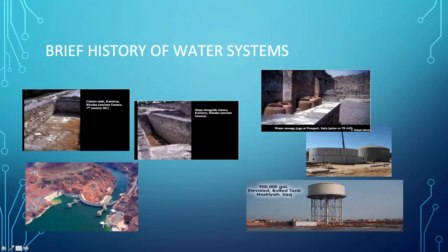These circular objects here are the intakes to the power plant and any drinking water supply that the dam is used for. Actually, no, not for drinking water. Drinking water intakes are quite a bit upstream of this photograph. As the water level goes up and down in the pool, the intakes have different inlets at different elevations. It plays the same role as the stairs here.